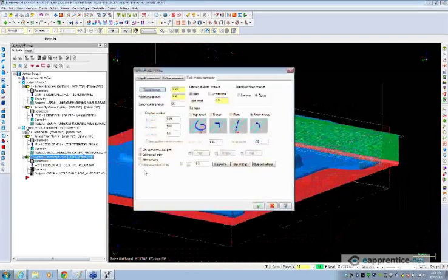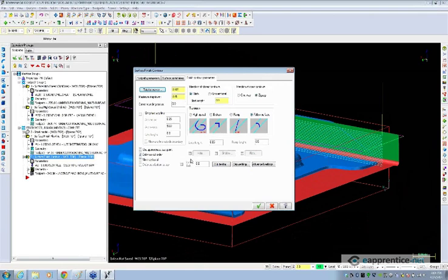Okay, so last thing that we would end up doing here is adjusting the direction, but we can also do our entry and exit arc and line. I have to go to broken, but once I go to broken, I can enable the entry, exit, arc, and line. And so here, this is my entry, exit. I can tell it allow arc and line outside my boundary, so it will let me get away with that. And now, instead of having to adjust these surfaces here, I may be able to just do that.